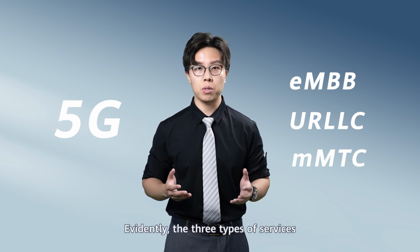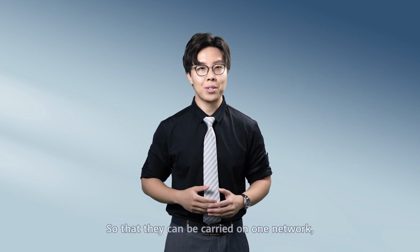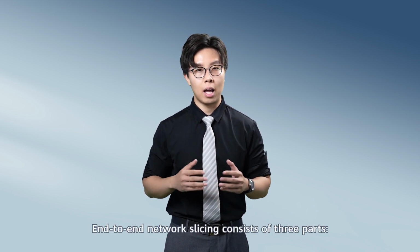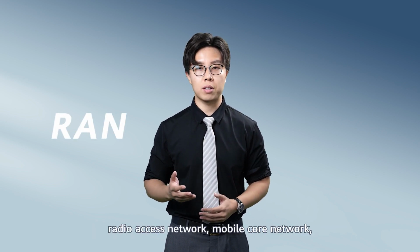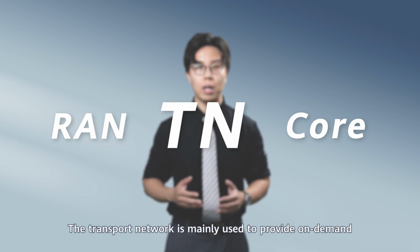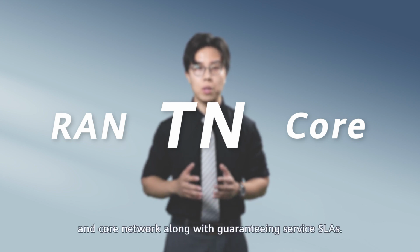Evidently, these three types of services have quite distinct requirements on the network, so that they can be carried on one network, 5G introduced network slicing. End-to-end network slicing consists of three parts: the radio access network, the mobile core network, as well as the transport network between them. The transport network is mainly used to provide on-demand connections between the radio access network and the core network, along with guaranteeing services' SLAs.